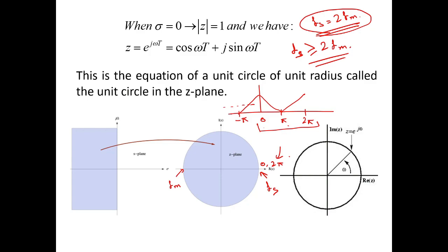Mostly whatever components we use are not ideal. So in the low cost ones, the ideality will be much further away. In those conditions, there would be some spectral leakage, and there would be mixing up of these frequency components, and this is regarded as aliasing.